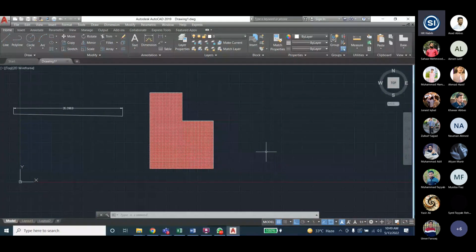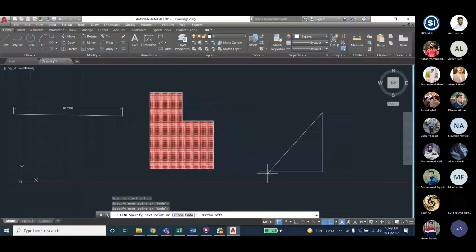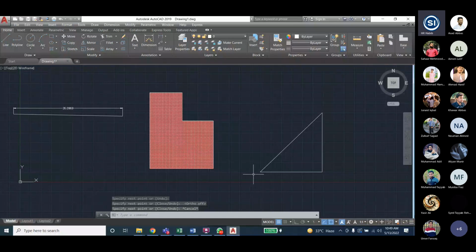In this way you can change the color, everything. Now you will dimension it, and also draw another right triangle. Just use the Line command and go here, for example, like this. Right triangle, one is a right angle, then switch off Ortho and then join the last hypotenuse line. Okay, hypotenuse. So switch off Osnap, because you cannot draw a hypotenuse with active Osnap. Okay, so this right triangle is drawn.